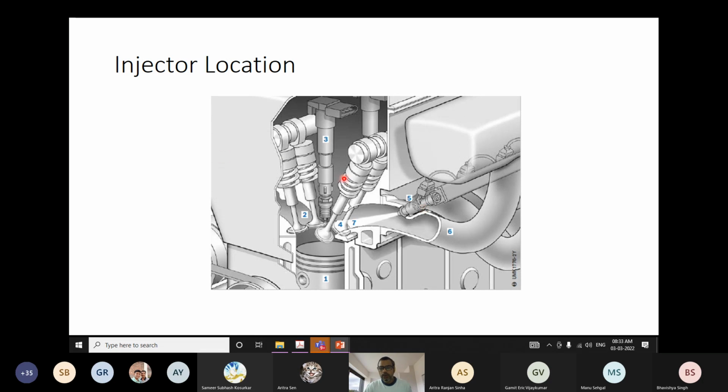Obviously each system has advantages and disadvantages. When we compare with the carburetor, we don't have direct control over the fuel injection because it is based on the pressure difference created inside the carburetor. But when we shift from the carburetor to the MPFI, then we have some control. We can control when and how much we inject, so we have direct control over the air-fuel ratio. But it has certain limitations also, one of which is valve wetting. Now, how can we avoid this valve wetting phenomenon and have even more control over the engine?